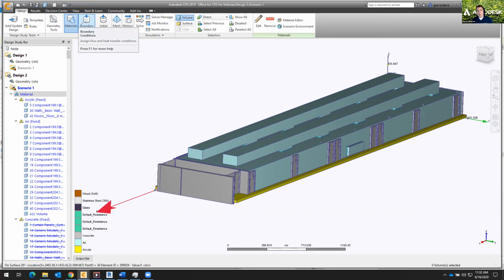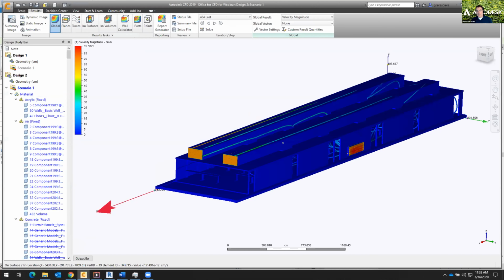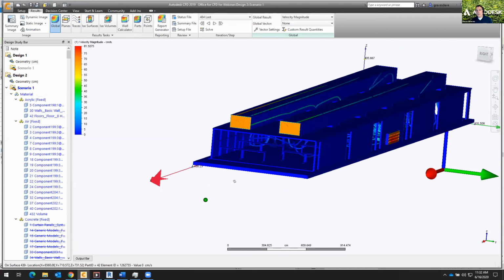So what are our boundary operating conditions? In this case, maybe I could put something like a flow rate in here. We can talk about doing things with contaminants in a little bit, but what do I know about the building and how it's going to perform? Typically for returns, we'll just have it open atmosphere, but you could have a closed loop system. It's definitely within the capabilities of the tool. Once I run these results, we're actually able to start visualizing the flow paths in here.